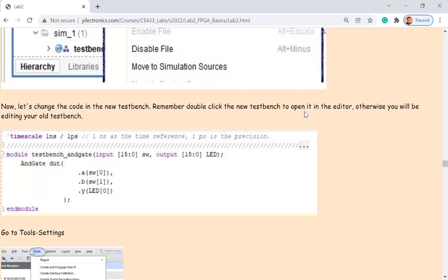For example, if you download the constraint file from this website, maybe, I'm not sure, because there are many different versions and options, the uppercase LED in this example won't work for the constraint file you have, because these are lowercase in the constraint file. I have to make the changes to the test bench over here to make it work. All right, that's the one thing I want to let you know.